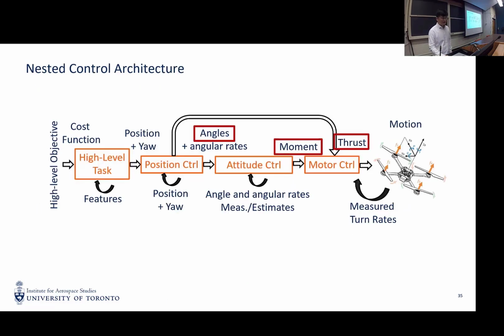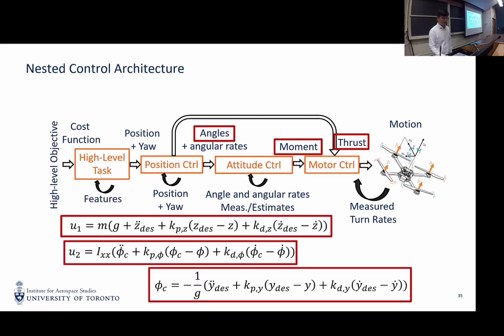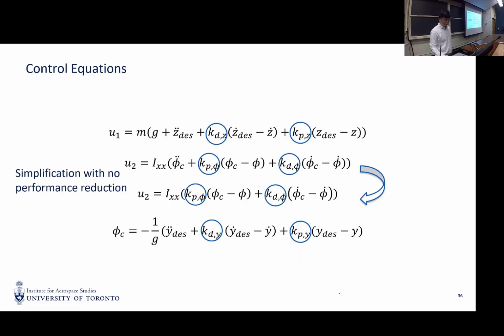Okay, that's a very basic concept of three controllers. One is to control the Z motion by using the lift adjustment. This one is a horizontal control motion by adjusting the roll angle. And finally, if we have the roll angle, we convert it to a lower level command to control the angular acceleration of the Quadrotor, so that the Quadrotor will tilt according to our command. Okay, so that's the control.